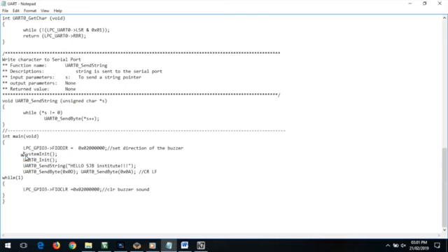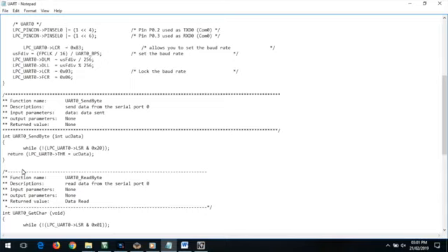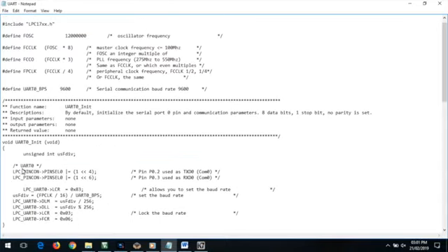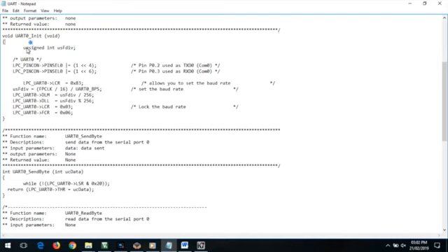So we'll start with what these functions are. First is the UART initialization, where we are going to set pin number 4 of the pin select 0 register equal to 1, so that we are enabling access to the divisor latch.